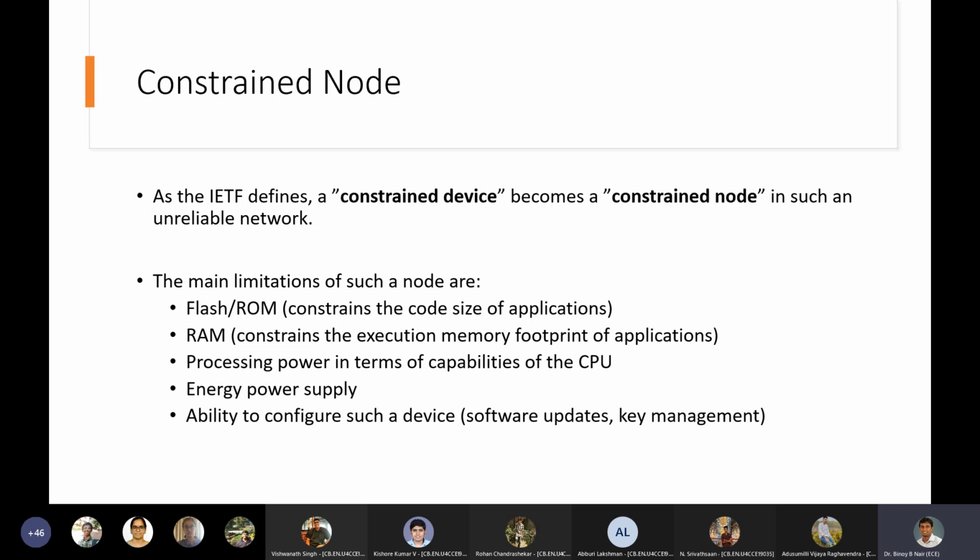So smaller devices will have a problem because you cannot put a lot of things in the storage. You can write them in the external memory, or in the flash space that may be available after the program, but you will not be able to use them dynamically. That is a problem you will face when you have a very small amount of RAM. So you will have to rework your code in such a way that you can do it with a smaller size of RAM. That is why the RAM is such an important aspect.